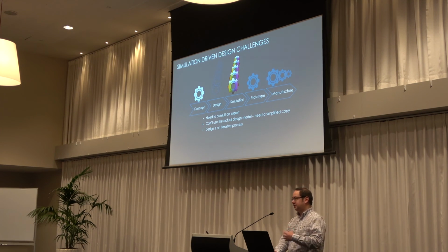So the point of this is not to give you that final validation check. It's, as a designer, here is my design, here's where the maximum load is. That looks like it might be a problem in that area. If I put this bit of geometry in here, a rib here, does that move the load somewhere else? Does that reduce the load? That's what I'm interested in. And that's what this tool lets you do really, really quickly.